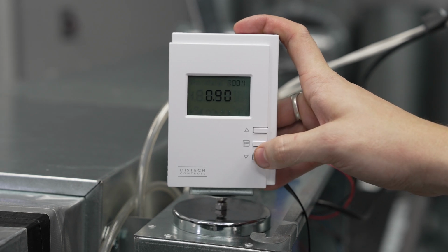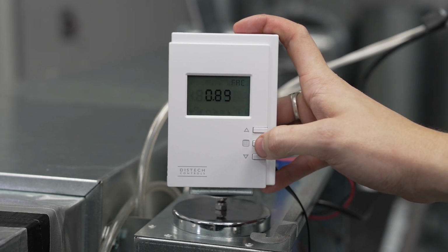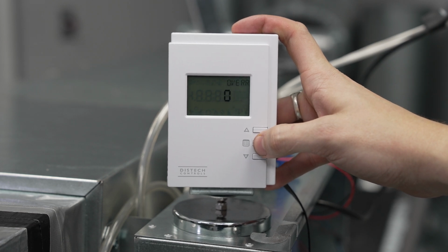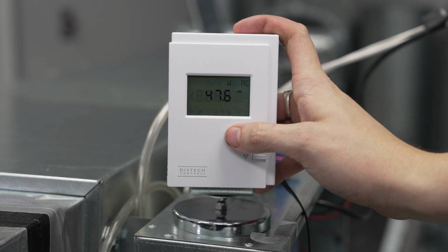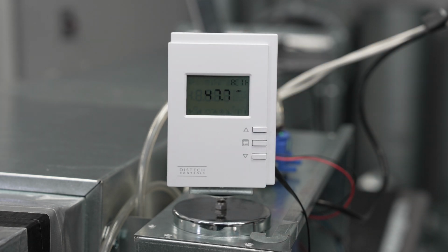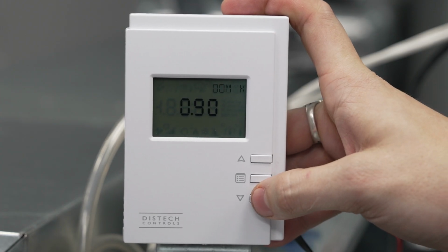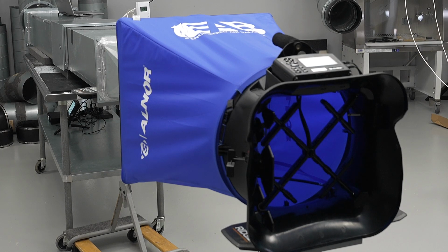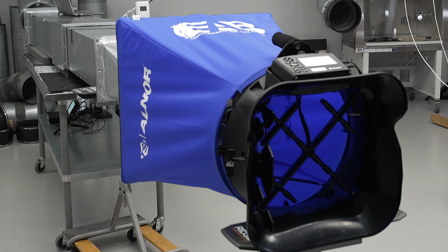Once our airflow is sufficiently close to our minimum airflow set point, we will re-navigate through the thermostat menus to get to our minimum room K-factor and put in the associated K-factor. In this case, both the maximum and minimum K-factors calculated were 0.89. So we'll put in that same 0.89, let our flow correct, give the unit another minute or two to get back to its minimum airflow set point.